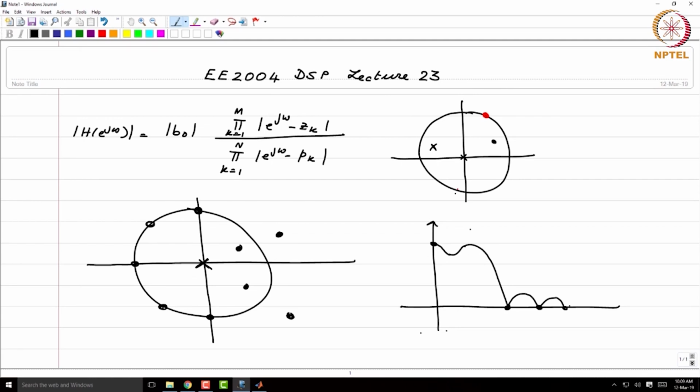So, here is an FIR filter which is low pass. Both passband and stopband behavior are governed by zeros, because there are no poles other than trivial poles to play with. And here if you look at this, the zeros off the unit circle govern passband behavior, and as before in the IIR filter case or pole-zero filter case, zeros on the unit circle govern stopband behavior.